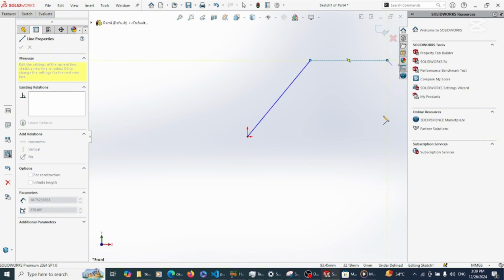But then this yellow box with a black straight line inside is showing you the relations, out of all the possible relations, that will be automatically added. That horizontal one you see with black is a possible relation, but it will not be added. It's just showing that it's possible. It's the yellow one that will be added.